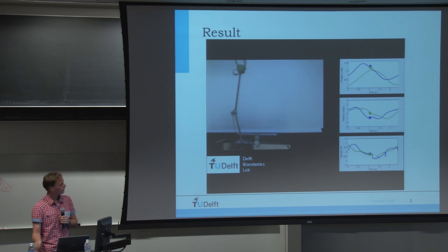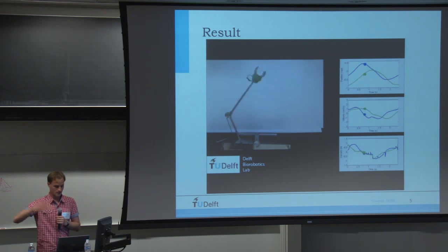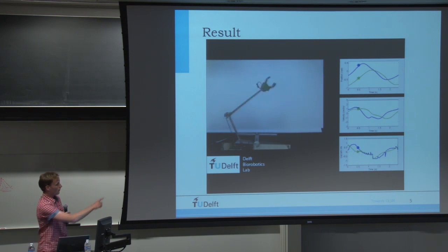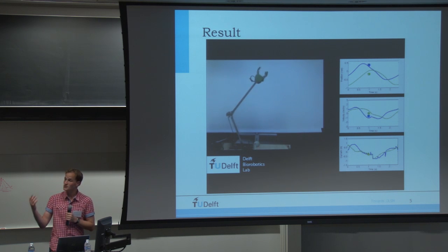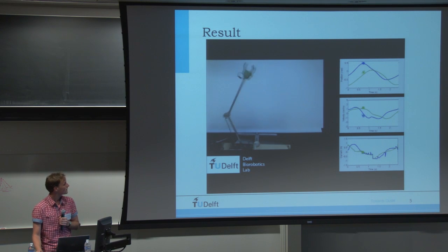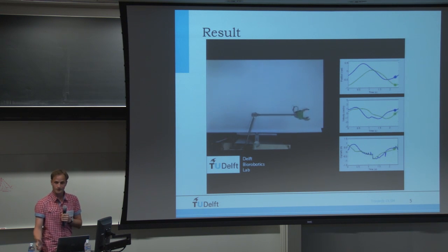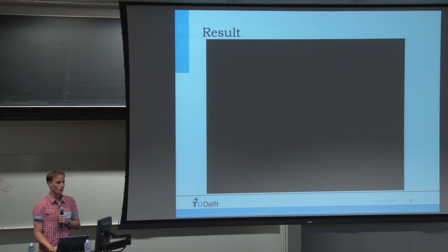and you will see that the balls of the position and velocity plots start to move around, where obviously we're doing open loop control, so the current stays exactly the same in the bottom graph. So I will repeat the same thing, give it an even more violent shock, and it waves around really heavily and really diverges, but it comes back after just 1 or 2 cycles, which I think is pretty neat. And yeah, so we have achieved with this something that we could call open loop stable waving.